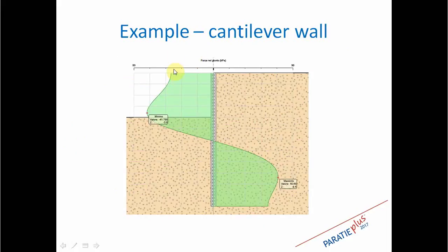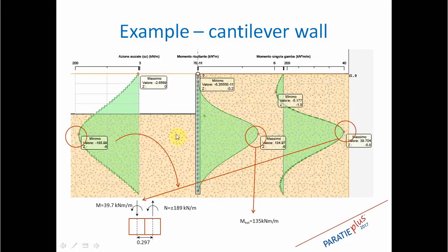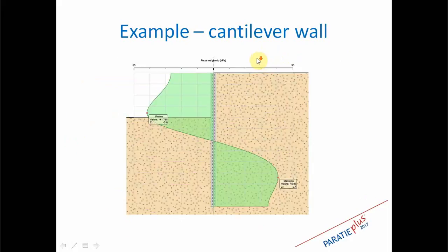And here we have the distribution of shear force along the joints. Of course, we can see that more or less, this complies with the shear force distribution like a beam, because here we have almost a zero strain, and here we change in sign when we have the maximum bending moment, like said by normal theory of structures.